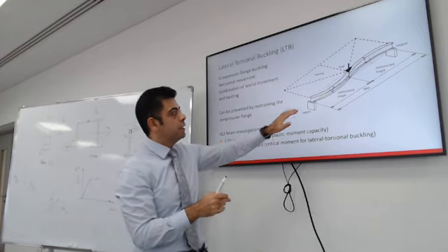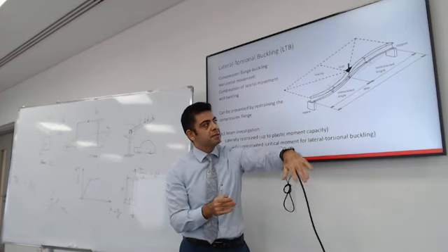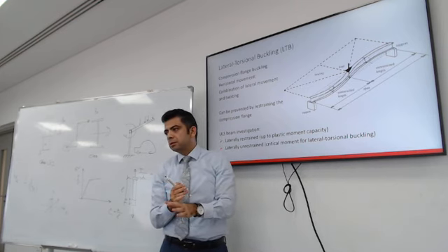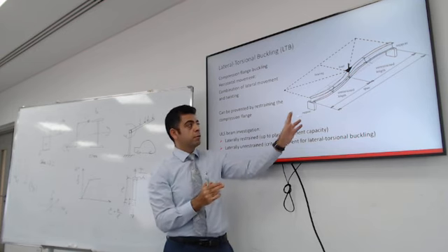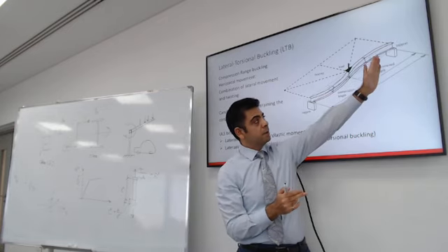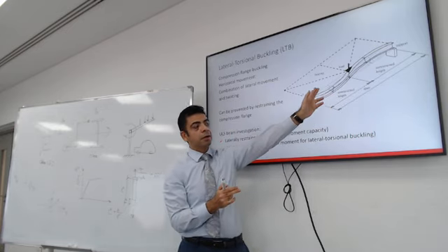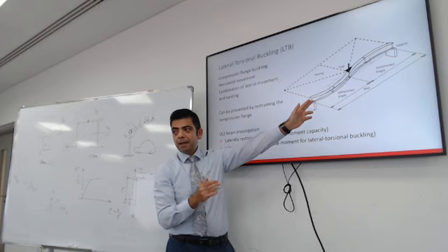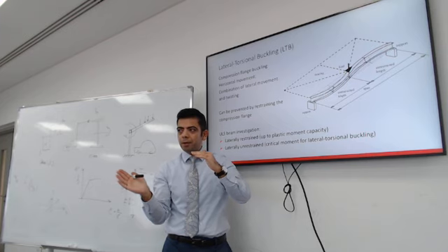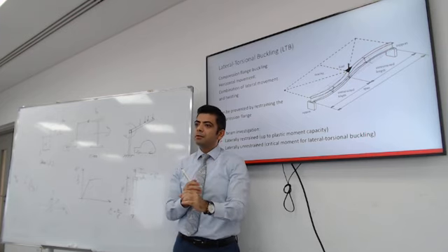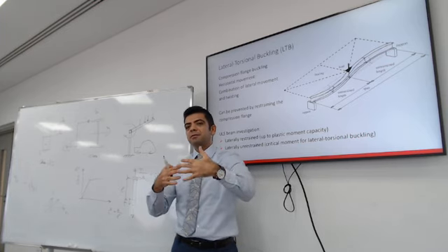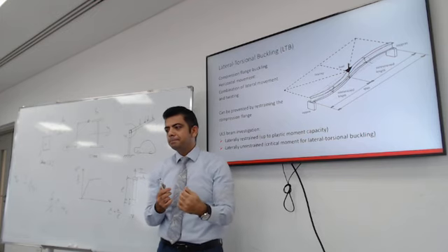So how do you keep a beam from moving sideways? To what? To the column or whatever it's jointed. So that's the column here. Yes. So if you weld it well here, you fix it here, and you fix it there. What about the entire length of the beam? Make a truss or something. So you can brace it to avoid lateral torsion buckling, trusses. But sometimes you cannot brace it. Can you think of an example where you cannot brace the beam sideways? That's a good question.